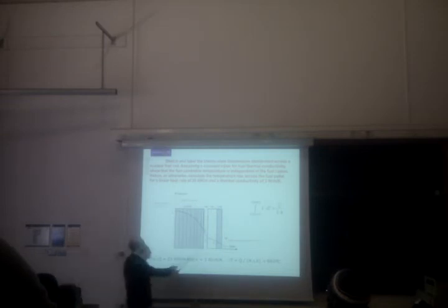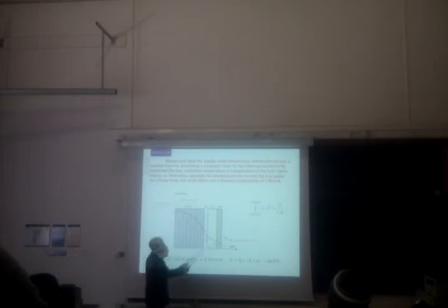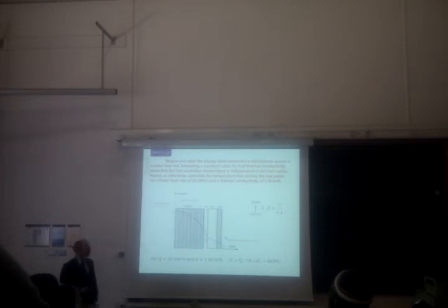Very small temperature drop across the cladding because it's a metal and a good conductor. And if the cladding has been in the reactor for a while, then it's accumulated an oxide there on the outside, so there's a small temperature drop across the oxide there.